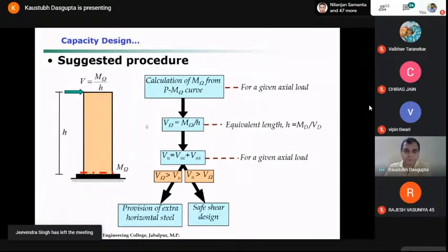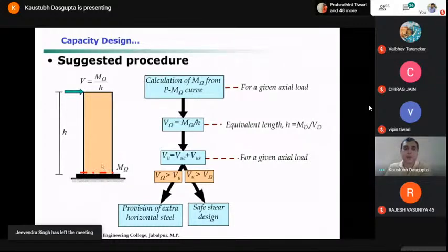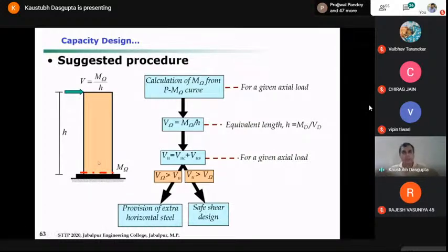And once you get the M omega, you find out the shear force, and then you can find out what is the shear capacity of this section, right? The shear capacity of the section will be contributed by both concrete and reinforcement. You have the horizontal bars in the section. These horizontal bars are the primary transverse reinforcement in the web of the wall.